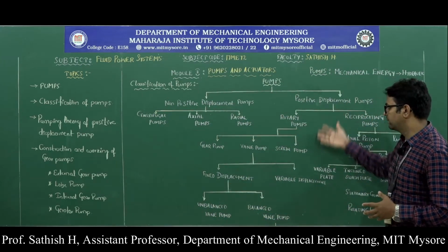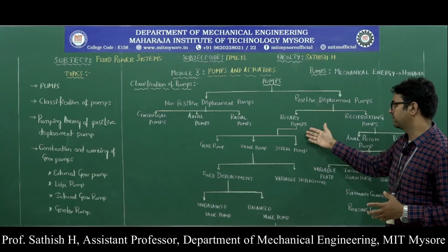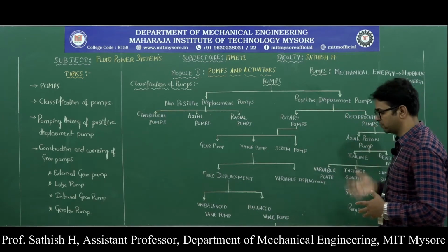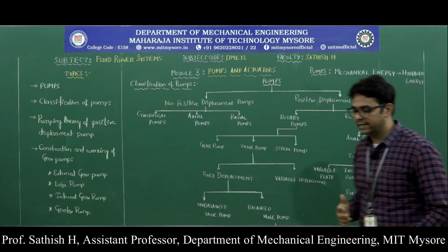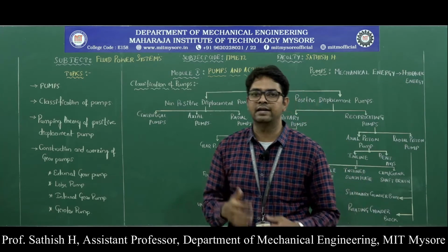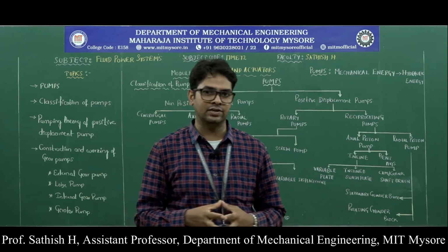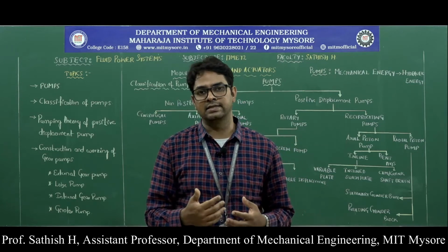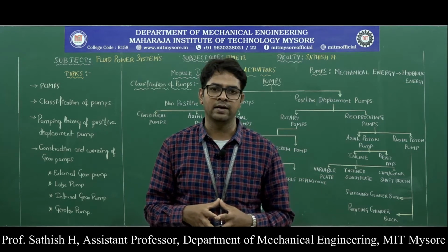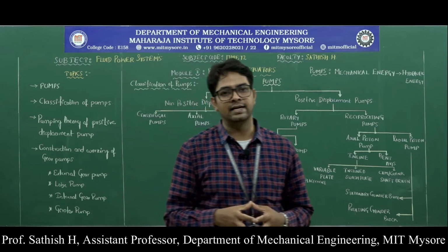Positive displacement pumps are broadly classified into rotary pumps and reciprocating pumps. What do we mean by reciprocating pumps? In a reciprocating pump, we have a piston and cylinder arrangement. When the piston reciprocates inside the cylinder with the help of a prime mover, a suction is created at the inlet of the pump.